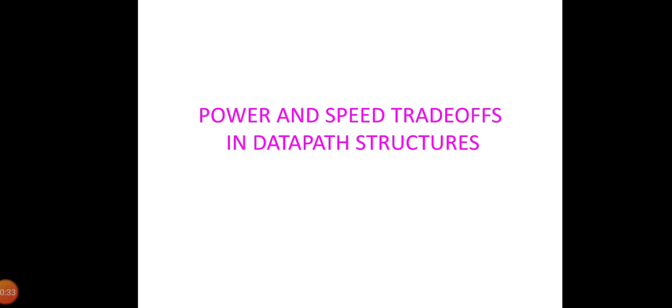are considered here. Typical digital designs are either latency or throughput constrained. A latency constraint design has to finish computations by a given deadline. Interactive communication and gaming are examples of such. Throughput constraint designs, on the other hand, must maintain a required data throughput. So, a 1000BASE-T gigabit Ethernet connection has to maintain a constant throughput of 1 gigabit per second.